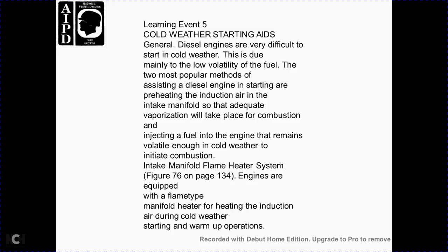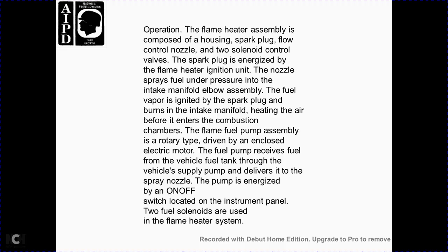Figure 76 on page 134. Engines are equipped with a flame type manifold heater for the induction air during cold weather starting and warming up operations. Operation of the flame heater assembly: the housing, the spark plug, the control knob, the 2 solenoid control valve, the spark plug, the engine drive, the flame heater ignition unit, the nozzle sprays fuel under pressure into the intake manifold, the elbow assembly.